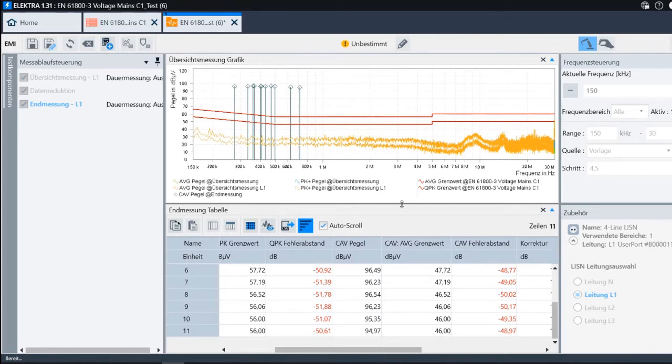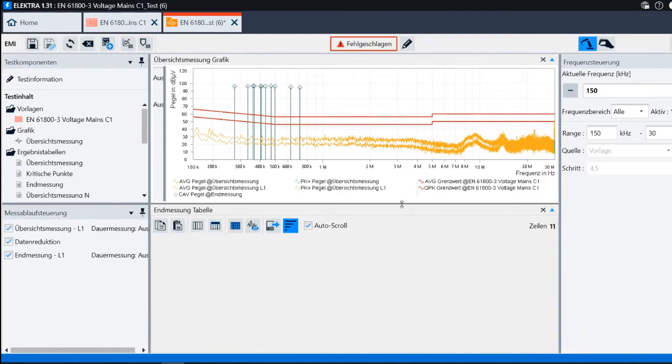And here you can directly see that the filter is working pretty well, and all the different measurement points are really below the limit, even about 20 dBµV below the limit lines. So our filter would pass the EMI measurement. The setup here is now a 2 kilohertz switching frequency with the 5 meter cable length and both shields attached to the system.